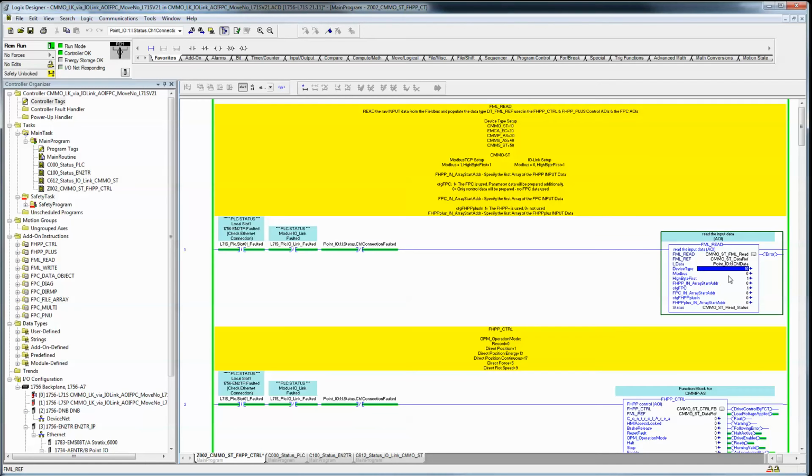And the Modbus and high byte first, if you read the manual, the IO-Link Modbus is equal to 0 and high byte first is equal to 1. So that's why this is configured as it is. The CFG FPC represents the fact that you are using the FPC channel, and then the read is set up.